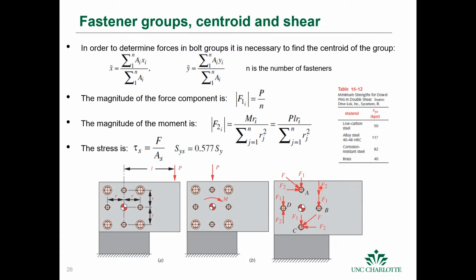Okay, so this bolt that's closer here is going to be experiencing twice the load, and that's because of the direction. This load tends to cause this downward force, but that load in this bolt pattern causes it to rotate in this direction, which causes a force that's opposite. Okay, so those forces oppose each other, and then this bolt here experiences twice the load.